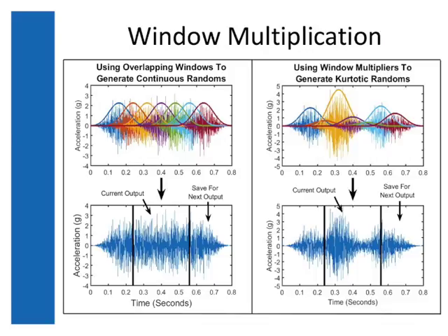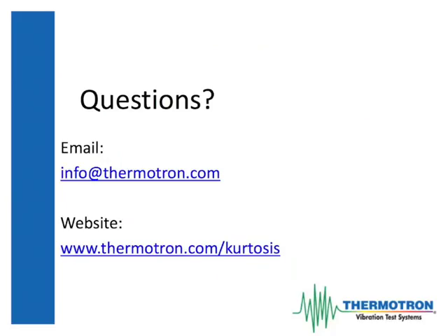I think most of the controllers on the market right now create a Gaussian random independently, and then they amplitude modulate it with some separate function, and then make sure that that never varies faster than a user-defined kurtosis frequency. That seems like an invitation to get the user in trouble to me, and that's why we went with inverse windowing. All right. Thanks, Ben.